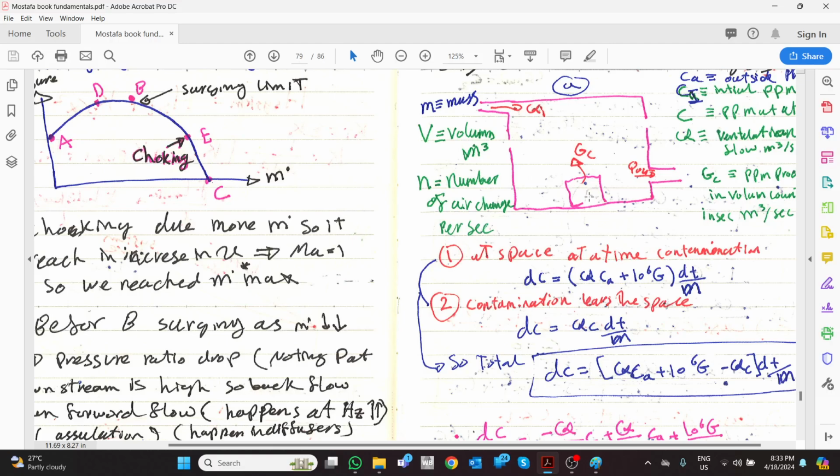This analysis can be done based on any condition, or you need to do the manual analysis for it based on any condition. Then you will take the CFD, which is going to show you the effect of equipment inside, the location of the point of exhaust, point of makeup, and whether it is a uniform distribution.